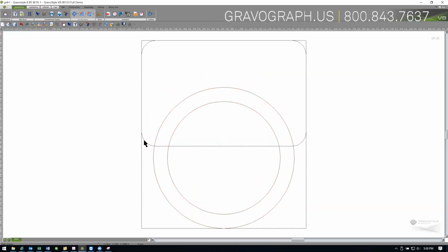So I will select the header and select the outside circle radius and group those together using the union tool. So this will take away the portion of that outer circle that I no longer needed, which protruded into the header. It also gives me the cutout radius that I need to form the inside of that tag where the push button switch or selector switch would go.